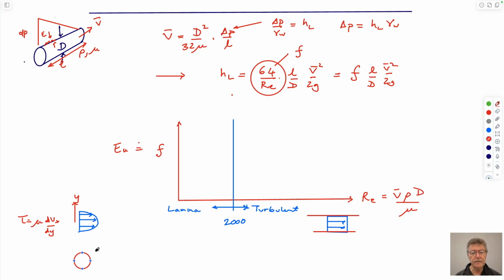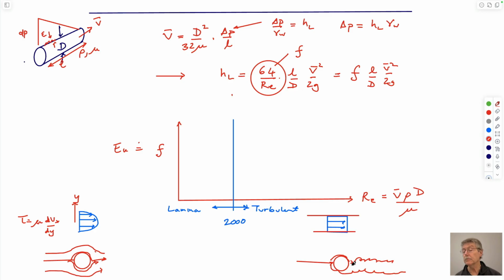If you have a turbulent flow, I think it's easier to think about it in terms of flow past, say, a golf ball. We know that if you have creeping flow, where all the losses in the system are due to viscosity, it hugs itself, and all the streamlines would be adjacent. We'll talk about this in terms of external flows. This one is different, in that, for want of a better drawing, there are these eddies that go behind it.